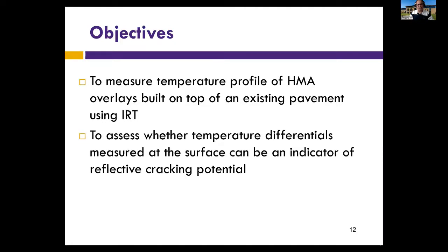To do that, we used infrared thermography, and at this particular location we monitored them during construction. And just to give you an idea, the joint is usually a very problematic location for the overlay, because this is where reflective cracking will appear.